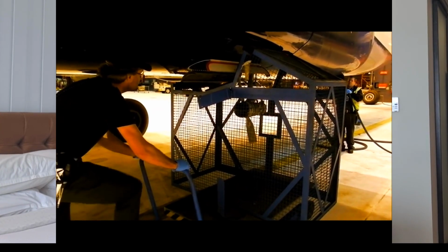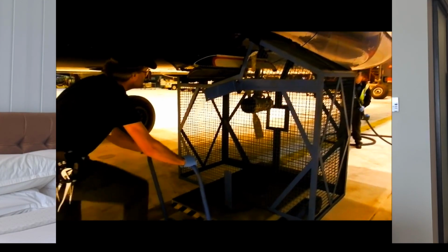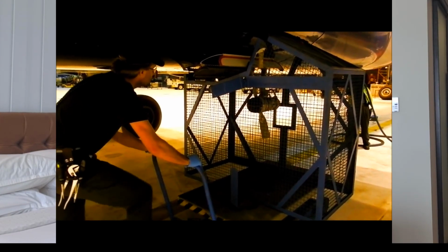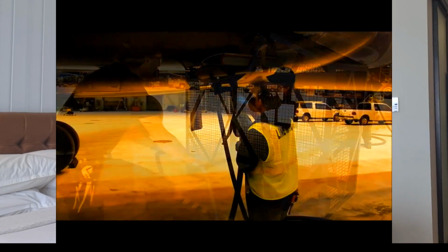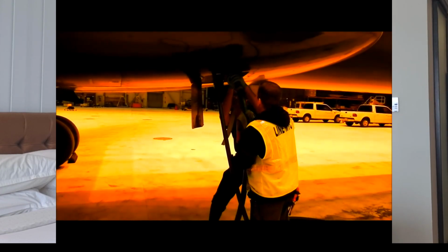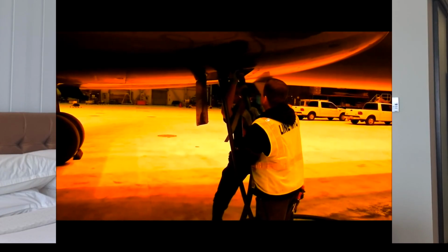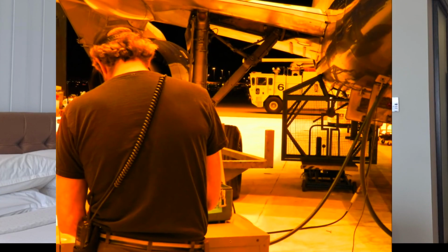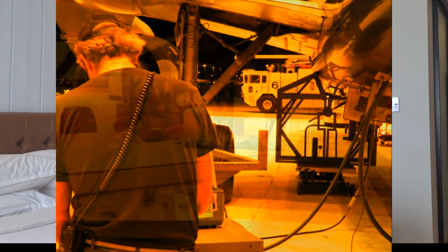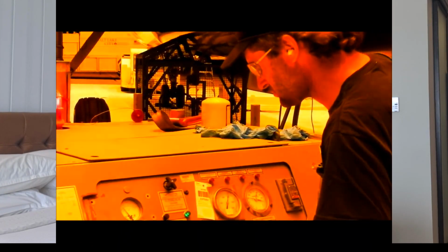So, when is a RAT test actually done? A RAT test is normally done during a scheduled maintenance inspection. It is normally done by backdriving the turbine to see if necessary supply is being actually supplemented to the crucial systems on board the aircraft. So mainly the generators and the hydraulic systems, which are crucial to flight controls, are normally energized by the RATs. Hence, this is actually inspected during the test.